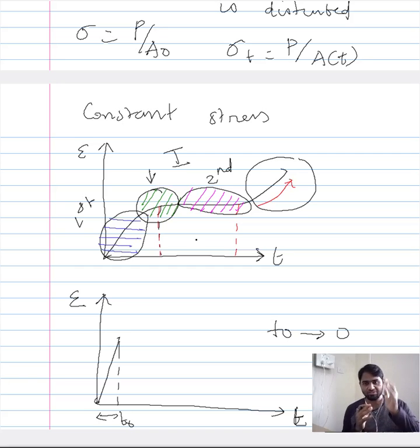One, the instantaneous elongation or instantaneous strain, coupled with a transient region where the rate of strain, or the slope of this curve, gradually decreases, and then it leads to the second stage of the creep curve, which is a constant strain rate curve, wherein the strain over a period of time is constant, and you ultimately end up with a third stage where the rate at which the strain increases is rather rapid, and ultimately it ends up in failure of the material.